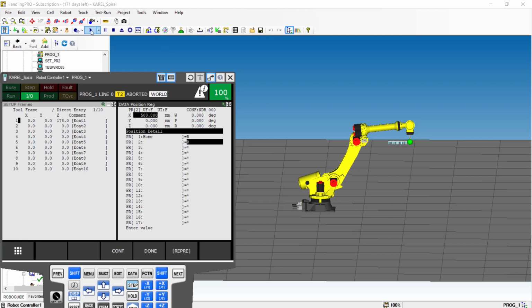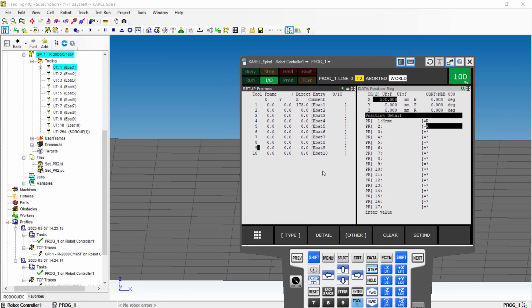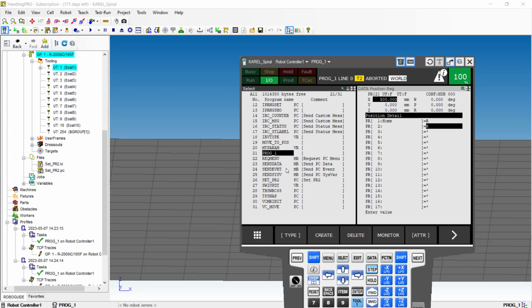We're going to run this one again. Go back to 0 and keeps incrementing by 100 millimeters 5 times. What we have done so far is a very simple linear motion, and we can go back again to analyze how this one happened. So we're going to select here our teach pendant program, move to position.